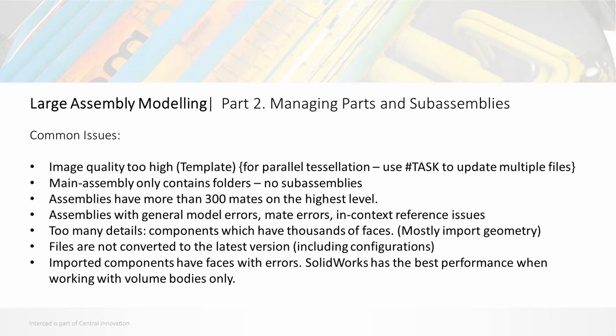Assemblies with general model errors, mate errors, or in-context reference issues. Make sure you're checking those things out. I'm going to talk about some tools that look into that in the 4th webinar. Too many details, components which have thousands of faces. Usually this is imported geometry, but again, as I mentioned with threads, make sure you have a simplified configuration that removes any unnecessary faces for your large assembly configurations. Files are not converted to the latest version, just talked about that. And imported components have faces with errors. That's what we started off with. SolidWorks has the best performance when working with volume bodies only.